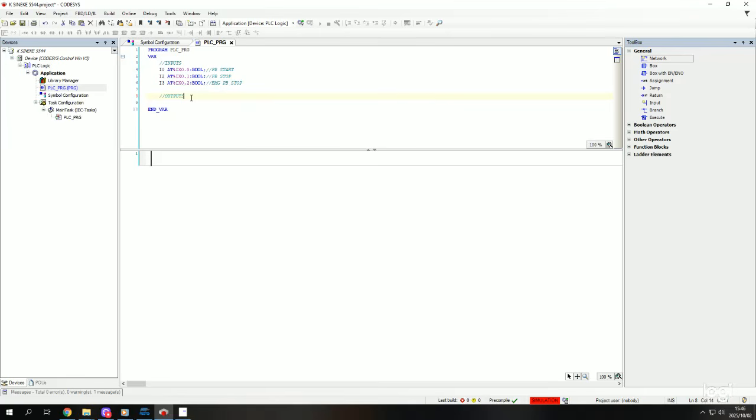In case of any bottlenecks that you are having in that particular station or machine or robot, you always need to insert your push button in your code, your stop button, as well as your emergency stop. So this is a basic code that we will work on, and then our outputs, they are represented as Q's. So Q0, then we change this I to Q, and our inputs are our push buttons as well as our proximity sensors or switches, and then our outputs, sorry, where you insert your solenoid valves.